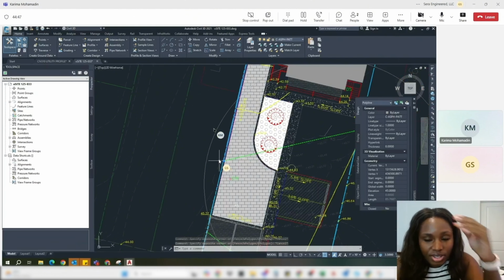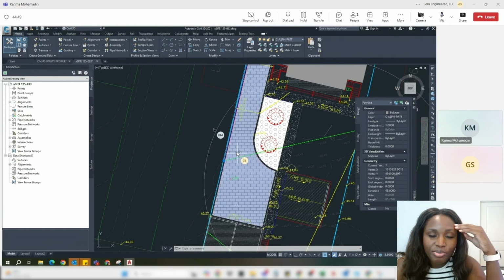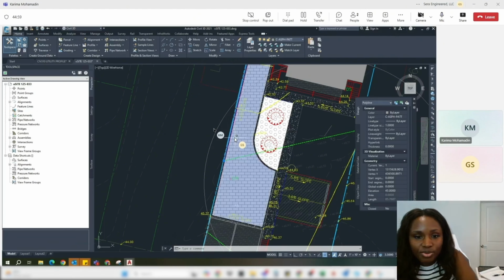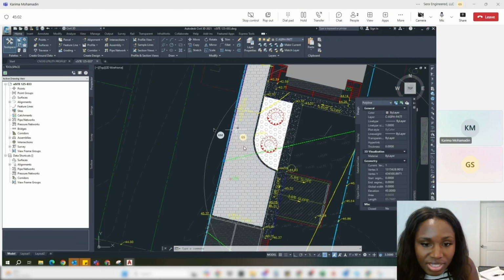And it's pretty aesthetic. The only reason we'd have to change this to an impermeable surface, and then it goes into there first, is because water needs to be treated. For an infiltration trench, the water needs to be treated before it can go into the system itself. With the permeable pavement, there's a choker stone, so that allows for the water to be treated beforehand.